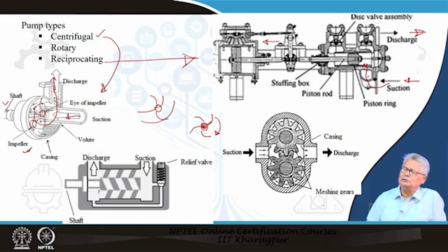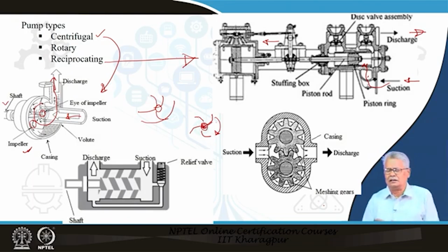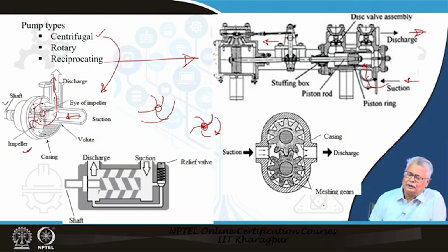In any basic hydraulics book you will find the working of a reciprocating pump explained, and there are various types. You can have dual acting, single acting, and different variations, and it could be driven by an electrical motor, a steam engine, anything, sometimes even compressed air.